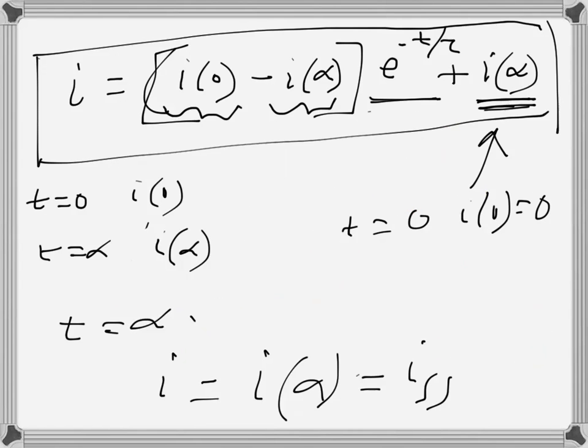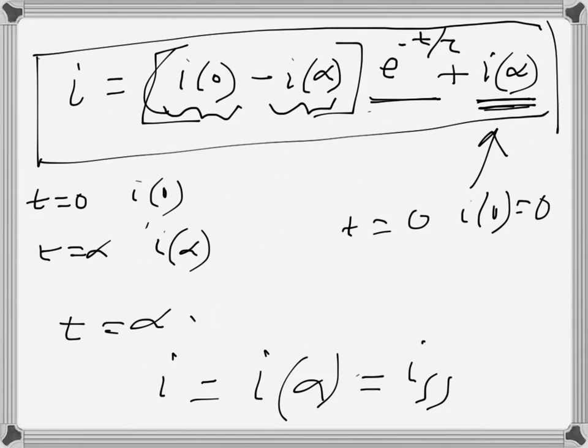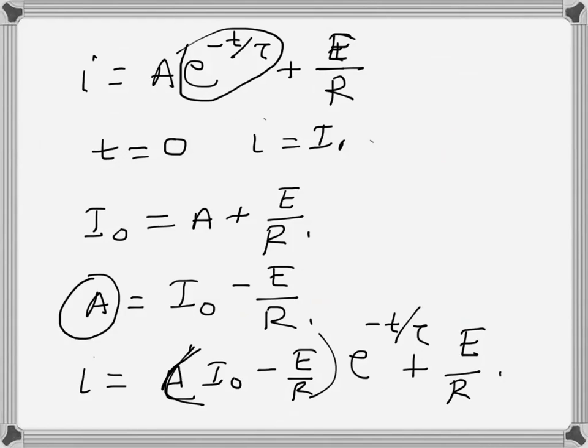I just tried to look at the same RL circuit in a different form. This is of course the result of the differential equation, but instead of writing the KVL as L di/dt plus Ri and looking at the natural response and forced response, we can write this form directly, because the transient part will always be exponentially decaying, and then there will be a steady state part.